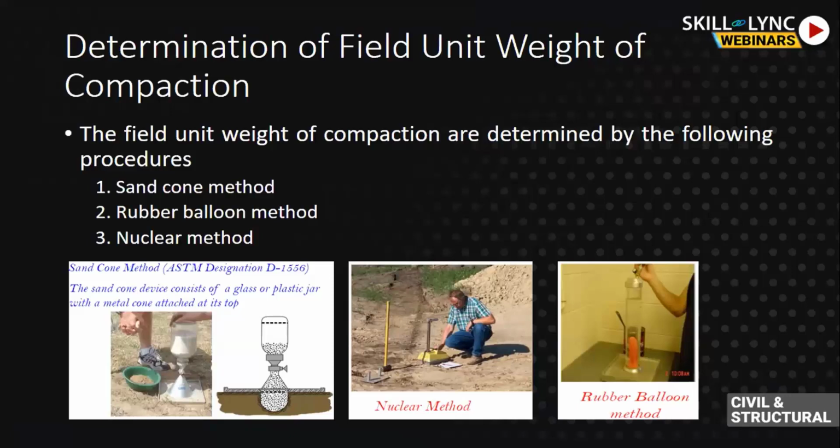And similarly, the nuclear gauge can be miscalibrated. Rocks can come in between the path, and surface preparation is required to carry out this test. And it's a backscatter method. Coming to one of the most important factors, the cost.